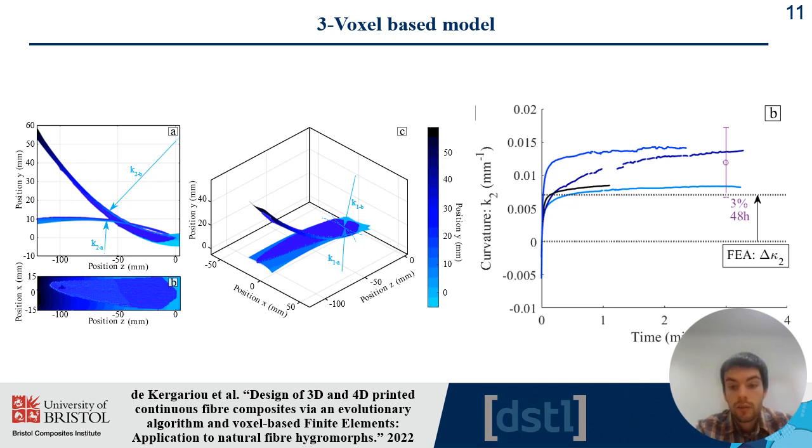However, regarding the quantitative deformation, we don't have the exact same value, and this is due to different things that we discuss extensively in the paper. If you're interested, I'm going to talk about two. The first one is basically the humidity. When you measure a specimen inside a glass box at 98% relative humidity, there are drops of water that go on the specimen and also on the box, and this perturbates slightly the measurements.